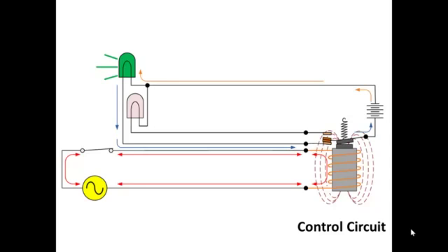So you see now with the switch closed, the green light is on, but the switch did not turn on the green light. The switch that the operator can operate by hand turns the relay coil on and off. The contacts controlled by the relay coil then switch between the red indicator and the green indicator, supplying power from the DC source.